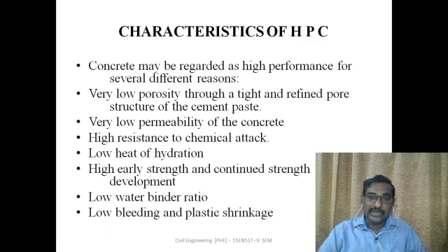The most important characteristic properties of high performance concrete are very high resistance to chemical attack, atmosphere and development bonding, low porosity, permeability, low heat of hydration, low water binder ratio, and almost segregation, bleeding, shrinkages are avoided.